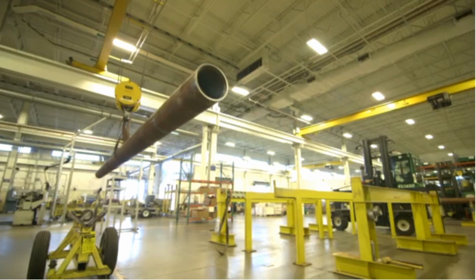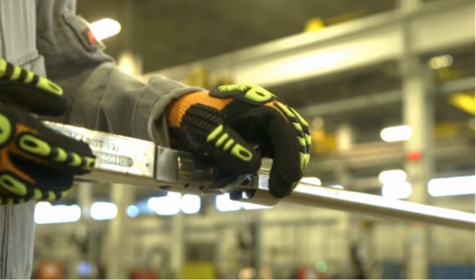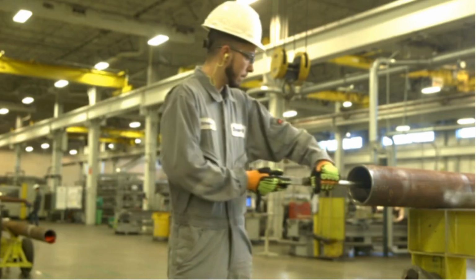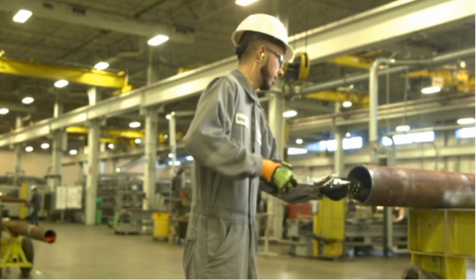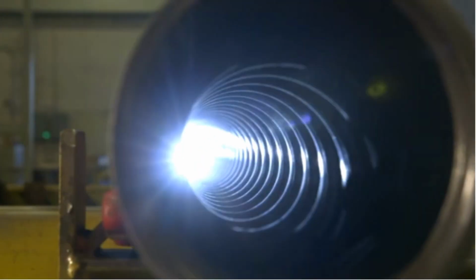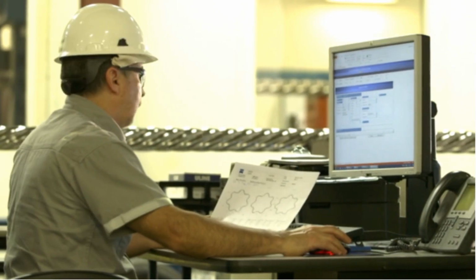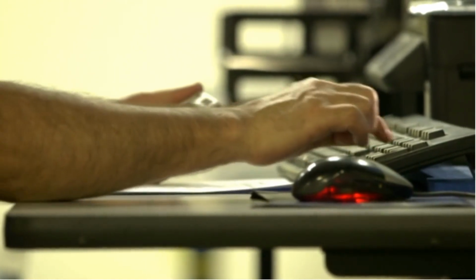at the connections. After cutback, the product is rigorously subjected to an all-points rubber inspection process to assure and record the built-in quality of the stator, and that the stator meets all reline manufacturing specifications and is so certified. At final inspection, Dynadrill verifies the integrity of the rubber's bond to the interior of the tube, ensures there are no imperfections in the rubber profile, and takes key measurements of the rubber to ensure proper fit with the rotor. All of these as-built records are reviewed and stored digitally in our proprietary computer database. The tube is then certified and delivered to the customer.